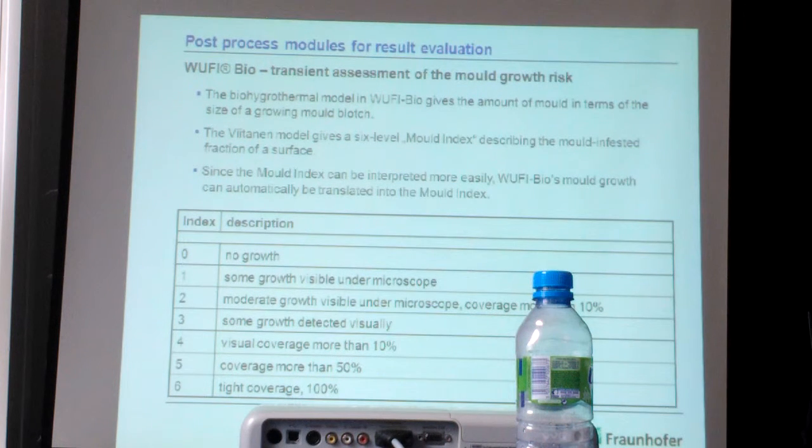No, but that's my whole point. If you have to do that, then in one sense WUFI analysis isn't very useful. Maybe it's useful to say there will be mould growth on the visible face of the internal surface, and that might be useful: don't do this because you'll get mould growing on your wall. But what we really want to know is what's happening behind the insulation.